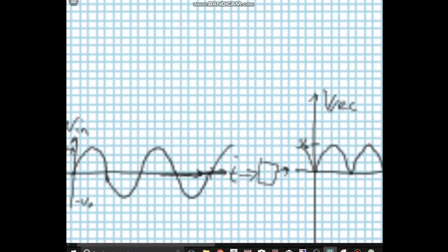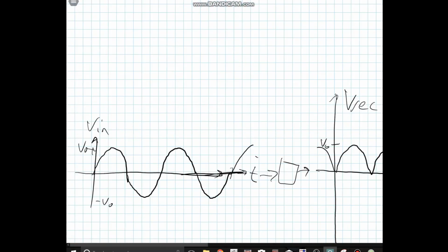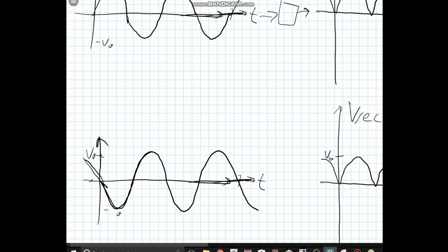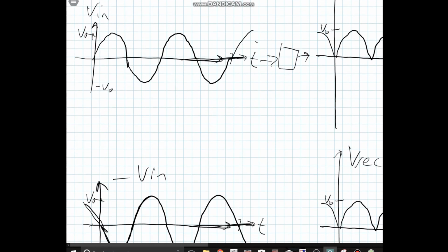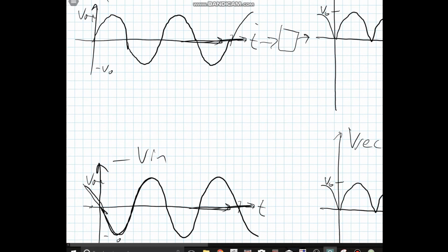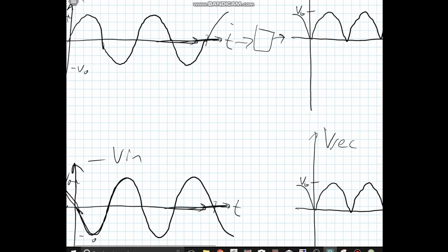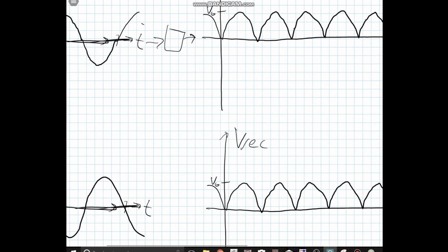So to be linear, our input would have to have homogeneity, and it would also have to have additivity. Now, let's just try a negative scaling first. If we scale the input by -1, we'd have this. This is negative Vn. And as you can see, it is opposite at every point. Scaling it by -1, you get a different input. But if you scale the input by -1, you're also supposed to get a negative at the output, but you still have this positive waveform yielded with a negative input.